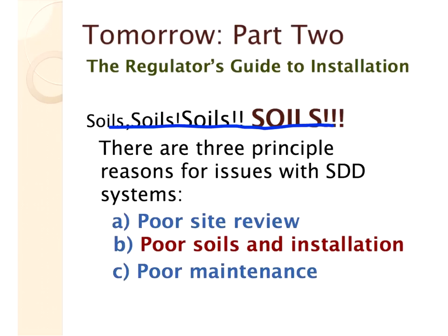Poor maintenance, of course, is a standard problem. If the treatment plant isn't maintained, if the filters aren't flushed, if the system isn't correctly flushed, it's a problem. I like 6 monthly. Every 6 months somebody should go out, check the treatment plant and check the drip fields. Some states require that, some don't. Again, this is a regulatory issue, but if I had my way, everybody would require 6 months.